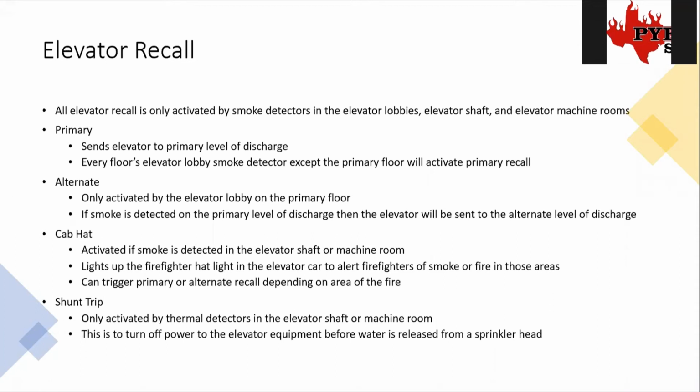But that's all. It's a light with that firefighter's hat in it, and that's to communicate to the emergency responders that smoke or heat or fire or whatever has been detected in either the elevator shaft or the elevator machine room. It's communicating, hey, this elevator is not safe to use because there's fire around its control equipment or around the elevator itself. That does not light up for any of the elevator lobby smokes. It only lights up for the machine room and for the elevator shafts. And it'll light up for heat detectors and smoke detectors alike.